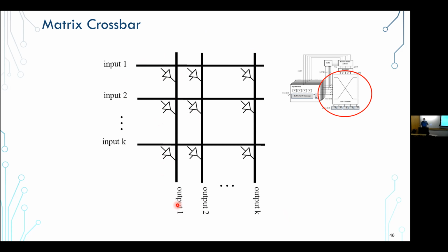It sounds very nice and compact, but it actually is not. The reason is that the moment you add the tri-state to bridge the wires, you have to go down from any metal layer via down, allocate some transistor area, via up, contacts, and all that adds space.